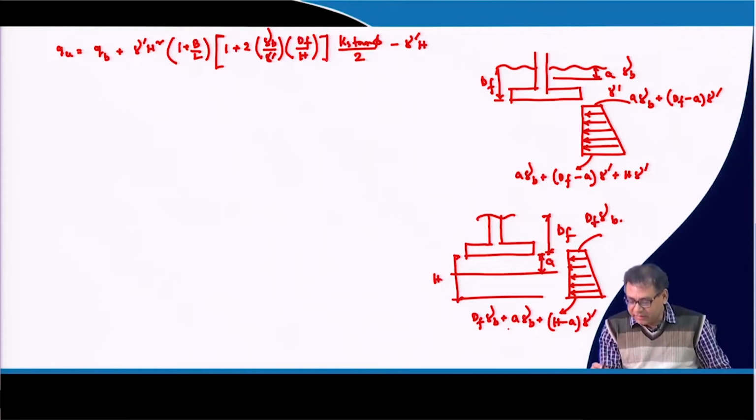And remember, do not always use this equation for the water table case, because we have to modify the equation and calculate this area depending upon the position of the water table. Depending upon the condition, you have to modify this, because in our example problem the water table is at the base of the foundation. So, I can use this equation, very clear.